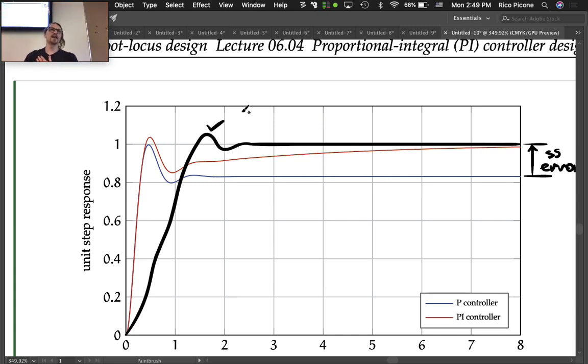They went with this design where it's going to take a minute to respond. But if they went the other direction and said, we want that initial quick response, then right when you hit that hill and started to drop speed, you'd rev up quickly and get close to your set value, like 58, really quickly. But then it would have a slower response to get that last steady state error out. So you might go to 62 and then 58 and bobble instead of being slow but exact.